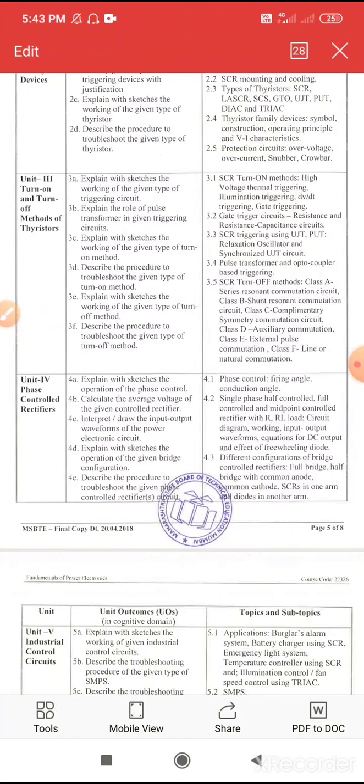In the diode, the output is fixed, meaning if we get an output of 5 volt, it will not be altered. In the phase control rectifier, by changing its firing angle or conduction angle, we can change the output; that 5 volt may become 4.5 volt, maybe 4 volt, maybe 3 volt. So phase control rectifiers are those rectifiers whose output is controlled by using the thyristor family.